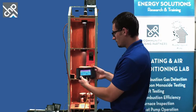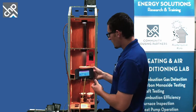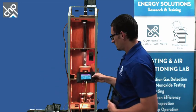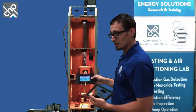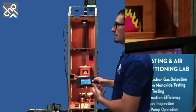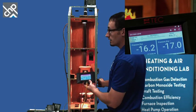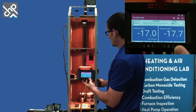So here I'm seeing, see that? Negative pressure throughout the building, top and bottom, because I've got my exhaust fan here. So if I provide some sort of makeup air, see the pressure, it's irrelevant, right? Goes away. It's because it's getting its air from the outside. So this exhaust fan and the fireplace are now competing for this air. So what I want to do here, if I crank it up even farther, I can really increase the negative pressure. This is going to be just outrageous here.